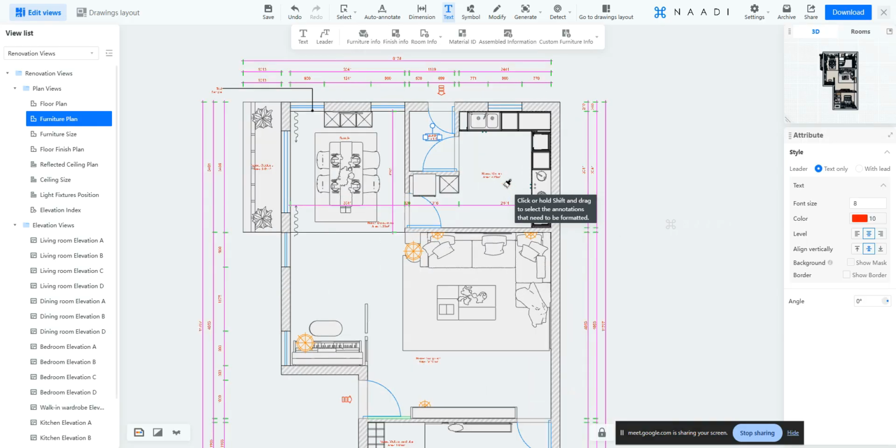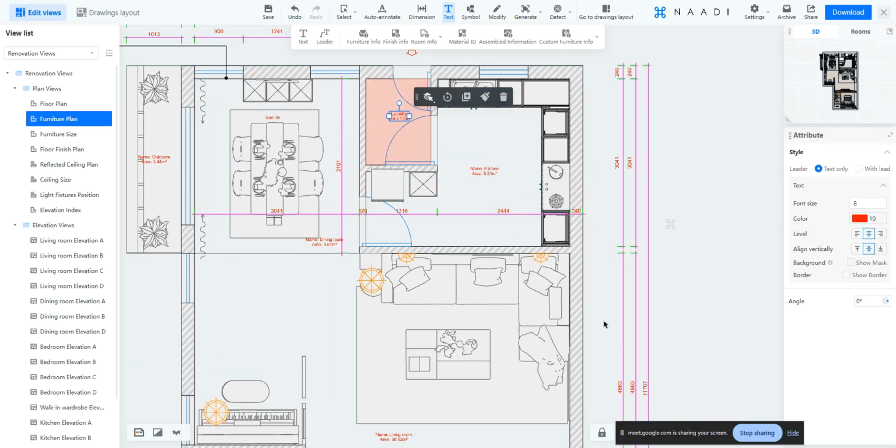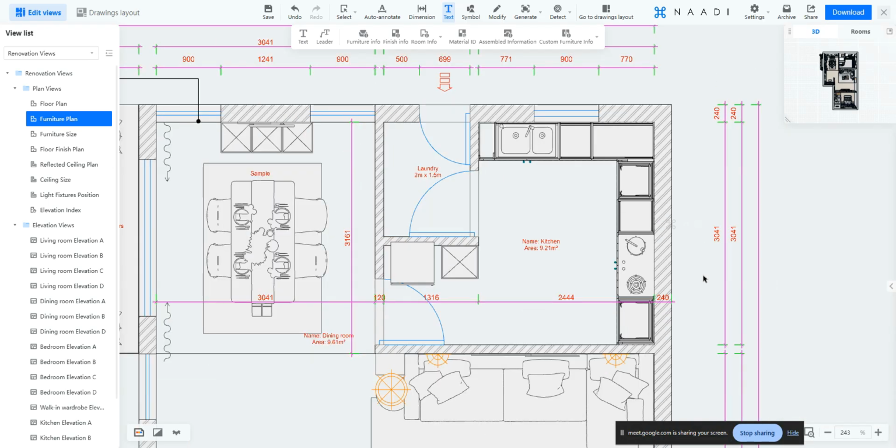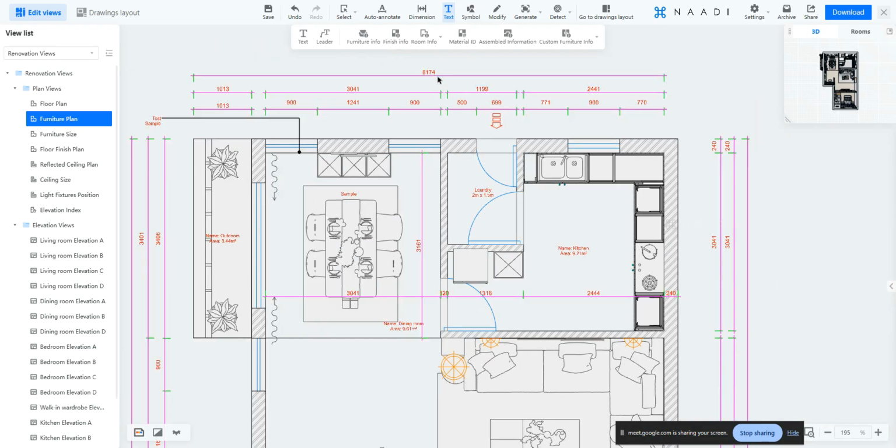Can you see, just in seconds? It is updated for the dimension, right? So this is what it is. So this way you don't have to do it on a massive scale. If you want, just edit the dim style for one text here, use the format painter, shortcut is here, and apply it. So it is almost like your material brush, same shortcut as your material brush too. So you can consider that as a material brush for your dim styles here. But yes, this is how you should be able to add or edit a new dimension or an existing dimension and take it to your requirement.